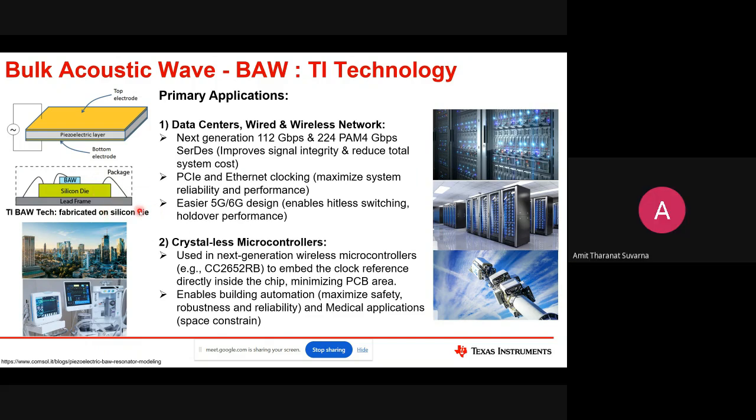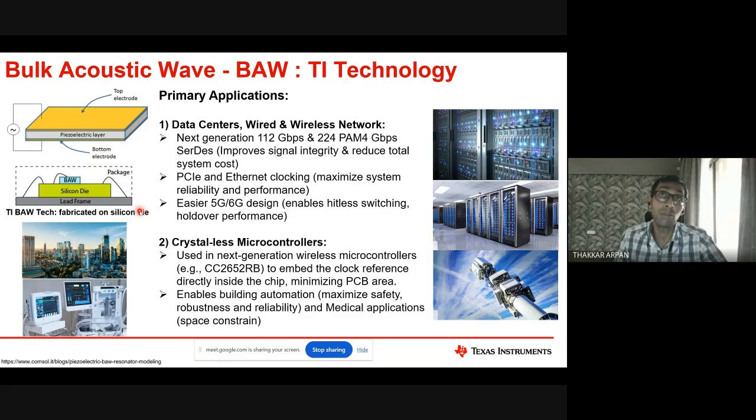So basically maintaining power integrity with respect to this. Yes. And it is much easier, ideally, if you have different PCBs, different ICs, you can easily do it, but then you need more area. So yes, that is always a challenge, and then there will be a spec on it that you can tolerate, let's say, minus 50 dBc of signal of the other channel on the first channel. So everything will have a standard that on this channel, other spurs should be lesser than this level, right? So we ensure that by all these techniques.